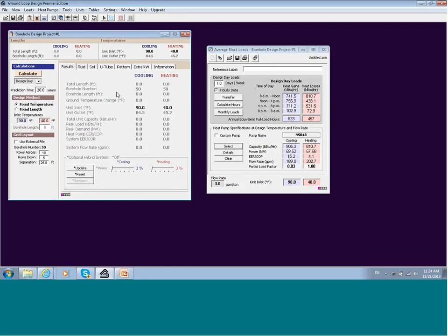Well, one thing to note is actually, if you were looking down here a moment ago before I linked, there were actually 4 sliders: a peak cooling slider, a total cooling slider, a peak heating slider, and a total heating slider. There were 4 of them there, and now there's only 2. The reason why there's only 2 now is because the program recognized that hourly data is in use, and the program can basically do all it needs to do with only 2 sliders rather than 4 with hourly data. But I'll come back to that in a few minutes.